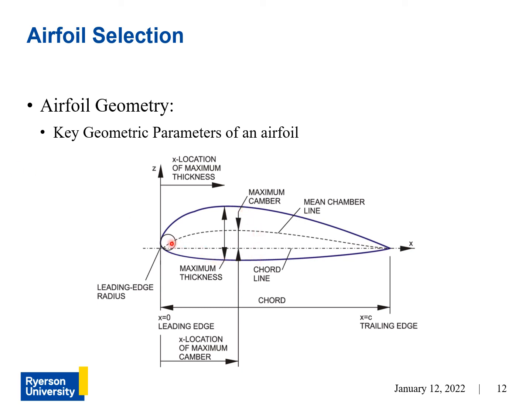Now, the camber of an airfoil, the amount it's curved away from its base shape, which would be a symmetrical airfoil, is defined by the maximum distance of the mean camber line from the chord.